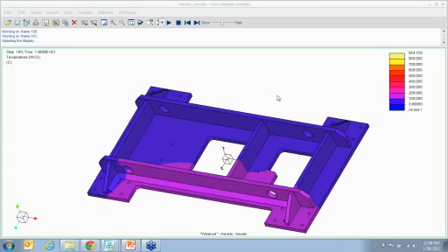Okay, Donald has two questions. The first one is, do you still have to run the preloaded analysis once and then adjust the value of preload and run the analysis again? No, sir, you don't have to do this. This will help you avoid running two analyses, which is the pre-stress analysis, right? You don't have to do that. And then he goes on to say, per help document in Wildfire 4, understanding preload and tensile force in advanced fasteners. I'm not sure if he can clarify that.